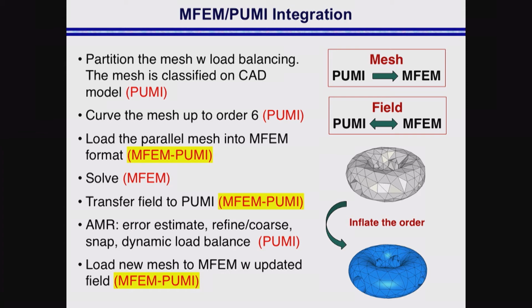The reason for doing the solution transfer with each mesh modification operation is it's much easier to deal with conservation requirements. For example, if I'm just refining an element, it's straightforward. I don't have to do any mesh-to-mesh mapping because I know exactly what I got. It's going to match entirely. If I'm going to do a coarsening, I know the portion of the mesh that's affected, and again, I can do the conservation with much less headache looking around the mesh.